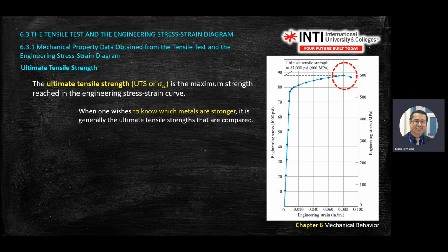After this, the material is no longer safe to use after this force. I'm from the aerospace industry, so if, let's say, an aircraft has a forced landing and the force is too big, although the structure does not break, the whole landing gear you have to change because it's already past the ultimate tensile strength. Externally it still looks like new, but something has changed in the properties already. At this point it has already elongated, it's already in the plastic region, extended a certain mm compared to the original, but it's not safe to use. You pull a little bit more, it will break.